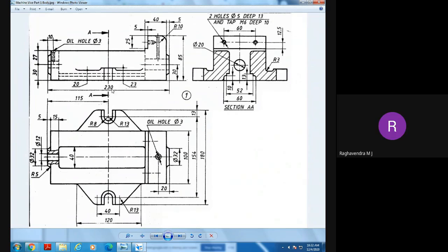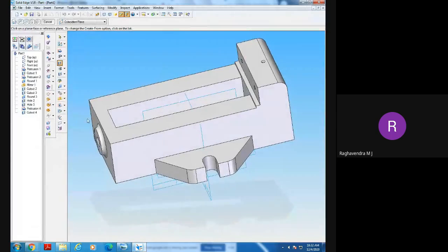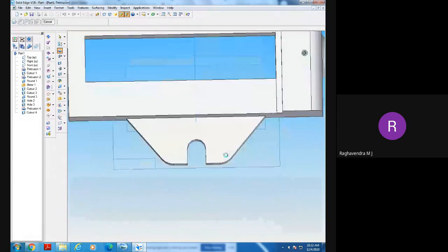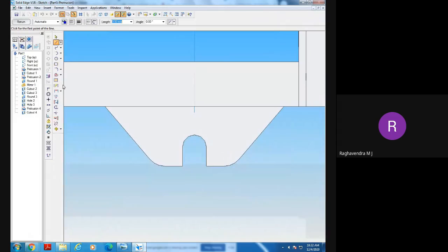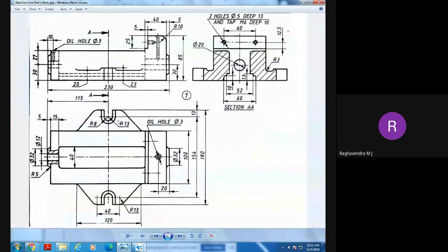3, sir. 3 millimeters. Therefore, from this top surface, he has done some small protrusion of 3 millimeters. From where? From this top surface. Go to protrusion option to select this top surface. Okay, now he has done some small protrusion of 3 millimeters thickness, and width is how much?